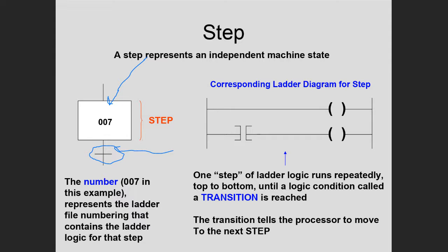Now, you would have this command on your screen, and when you double click on this box, it would open up a screen over here. Much like in your simulation where you can write your program in the edit window, you would double click on this instruction and an edit window will open up, allowing you to put in ladder logic.